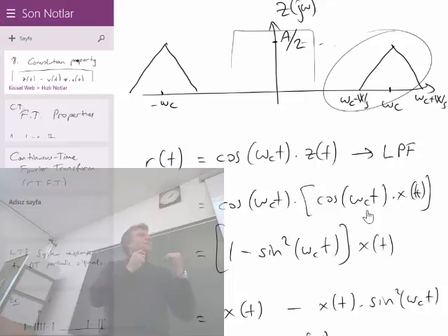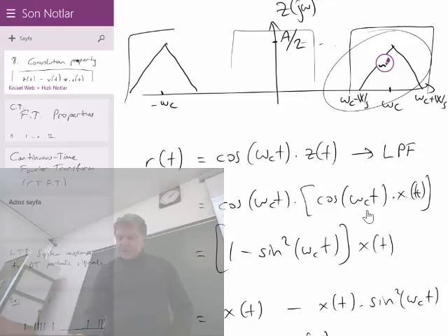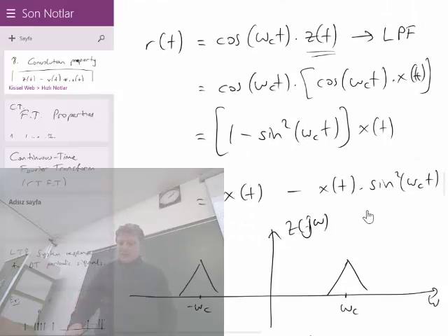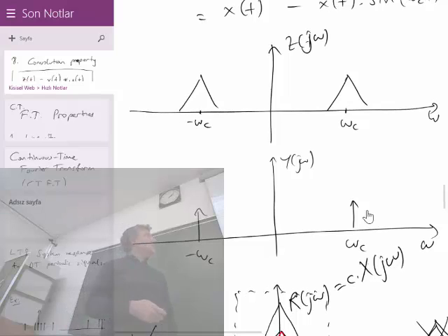So, when you tune to one of these signals, what your radio does is it applies a bandpass filter to take only these triangles, and then it multiplies your reception z of t with cosine omega c t again. When you do that, graphically what happens is the following. Your received bandpass signal is at the top, and in frequency domain you convolve with again these two impulses.